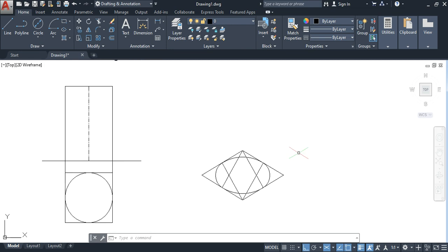isometric view of a circle in the isotop plane, and also we have to draw vertical lines now to get one more base. So we know, suppose if you assume this as a bottom base, so we'll get one more base for the cylinder. So for that we have to draw vertical lines from all these points. We know height is given 60, so we'll draw 60 mm lines here.